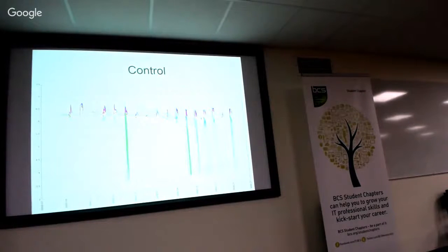After about a week, one of our nodes has dropped down to 3.5 volts, which for a 6-volt lead acid battery is death. So that node's effectively died. This was just using a simple regime with a 500 millisecond time cycle. It was on for a few milliseconds of that, and then off the rest of the time, so it was cycling itself around.